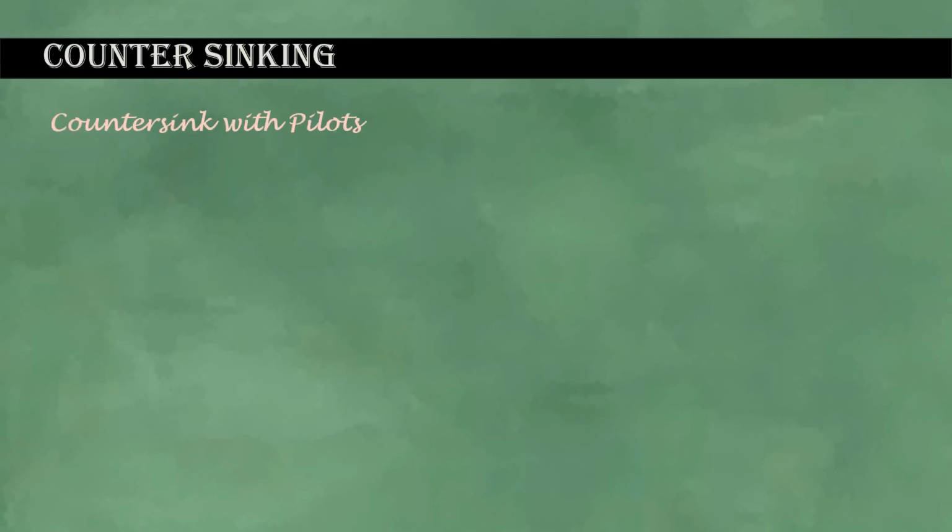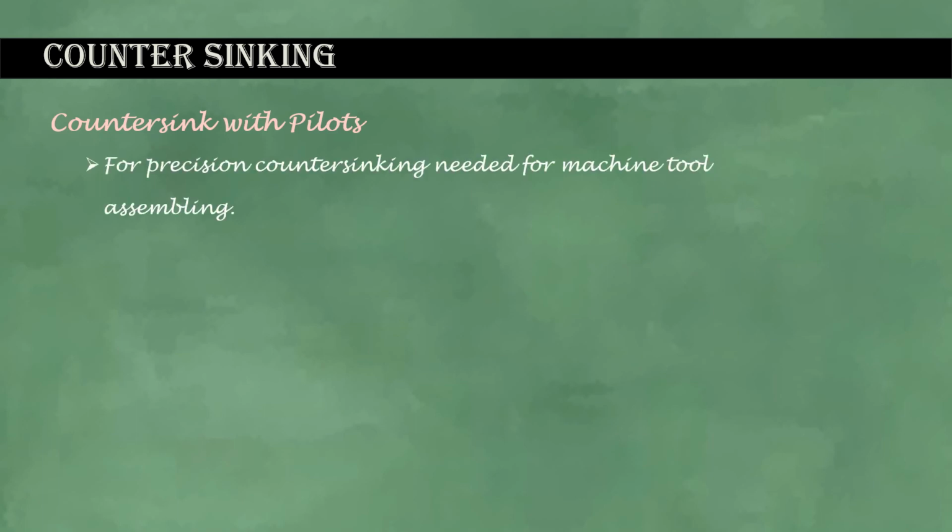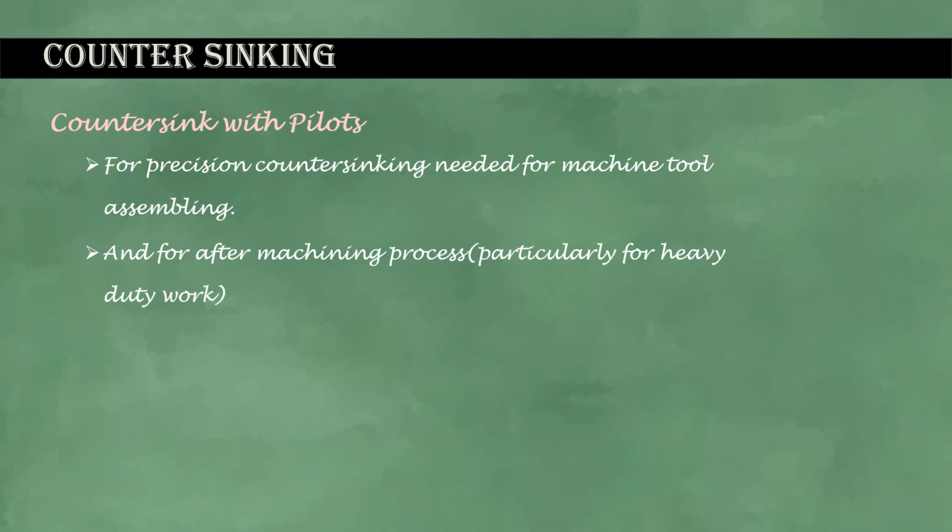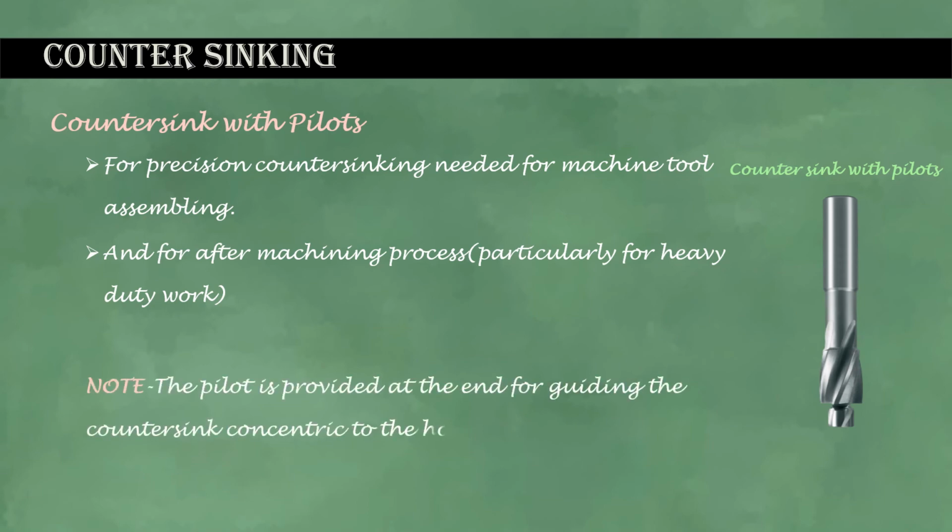Countersink with pilots, for precision countersinking needed for machine tool assembling, and for after machining process, particularly for heavy duty work. Note: the pilot is provided at the end for guiding the countersink concentric to the holes.